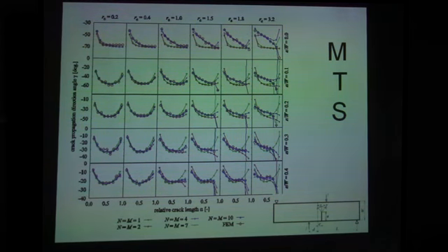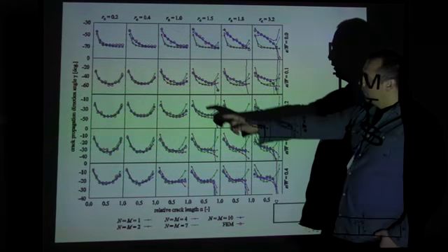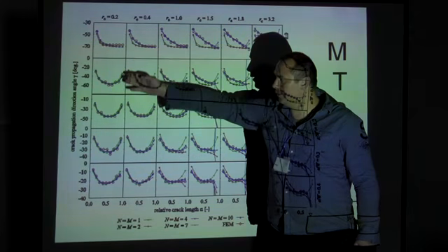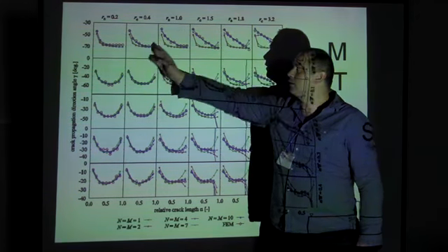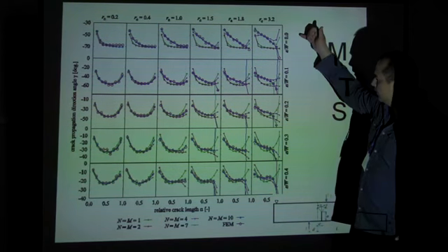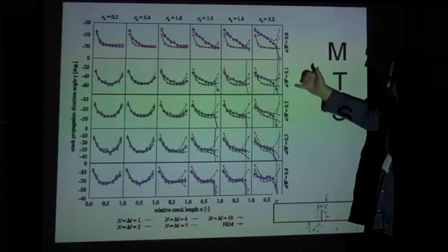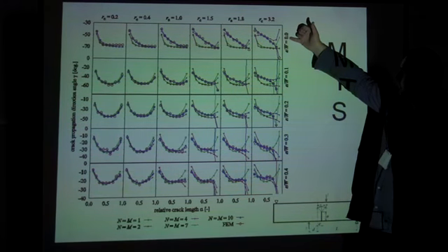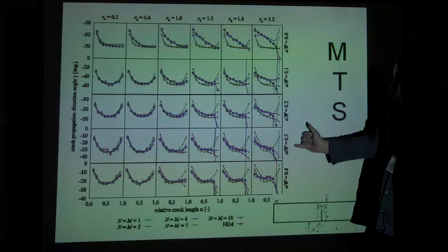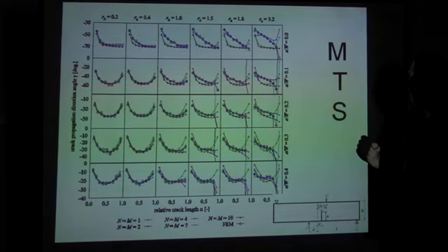Now you can see the result of the maximum tangential stress criterion. You can see in the table on the left side the initiation angle, then different distances from the crack tip, and as was shown in the figure, there are different eccentricities: 0, 0.1, 0.2, 0.3 and 0.4, where the crack is against the force.